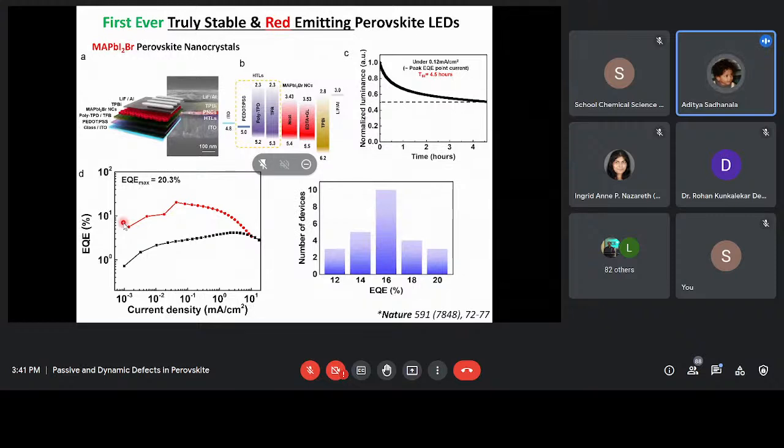So you can see by stabilizing the band gap, you can get really high efficiencies and very stable as well. This emission doesn't change; it's very stable for almost 5 hours of continuous operation. But in displays and all, these LEDs will be pulsed, so this stability will be extended very long. Okay. So this is one of the state-of-the-art results that we achieved by such stabilization.